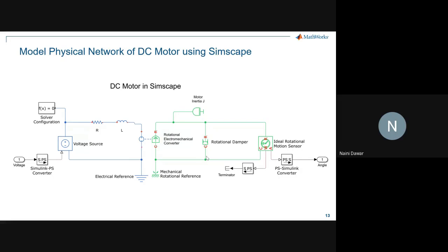And if we talk about a battery, since we're talking about a motor here, which is an electromechanical system, a battery is more of an electrothermal system, because the thermal effects are also involved. So in that case, you also include Simscape's thermal library to make your entire battery model, right? Similarly, we'll come to the power converters as well, which is an entirely electrical circuit.